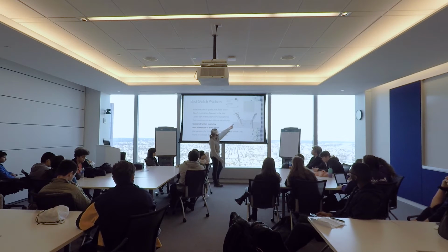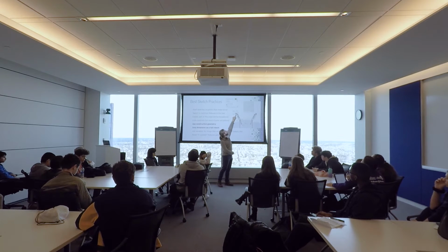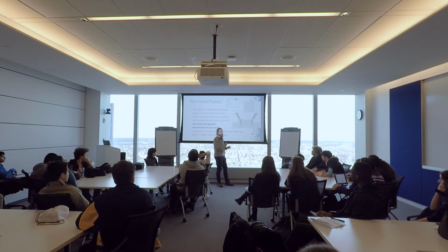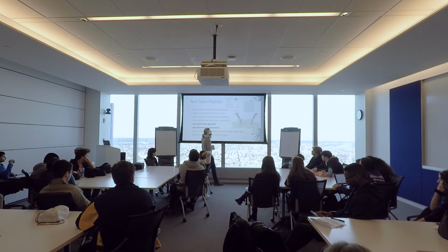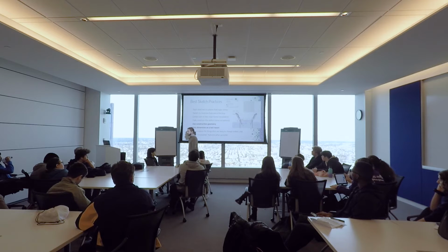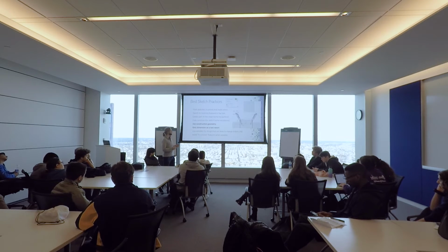So for example, in this sketch, I only dimensioned one of these diameters here. This is a bearing bore. That's an inch and an eighth bearing bore. So I know that all my other bearings are going to be an inch and an eighth. There's no reason for me to dimension each and every individual one of them. And the same thing for these radii. I only define the radius there one time, and then I set it equal for the rest of them. So keep as few dimensions in your sketches as possible.